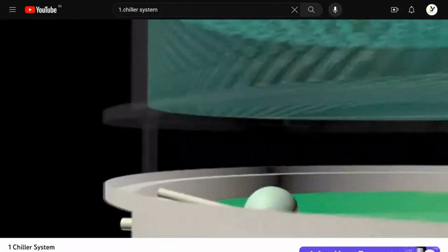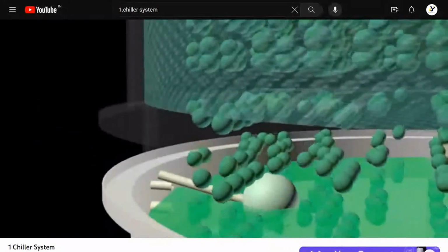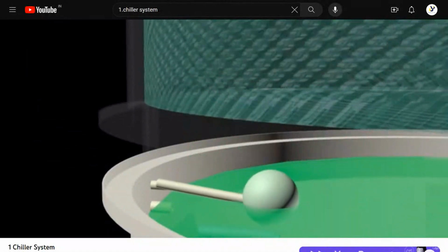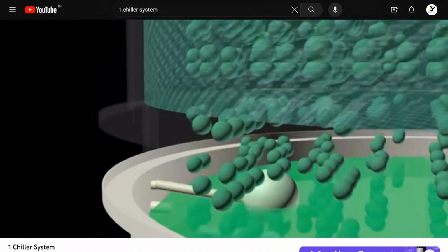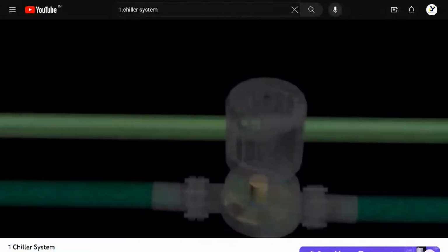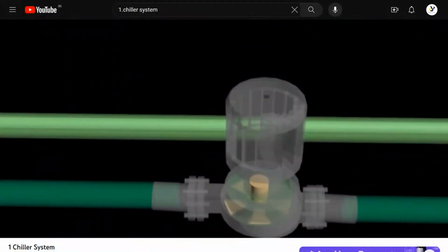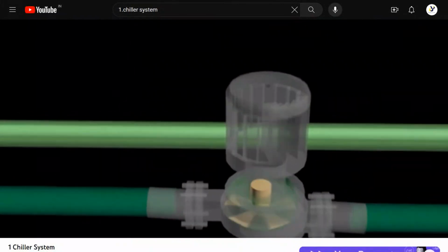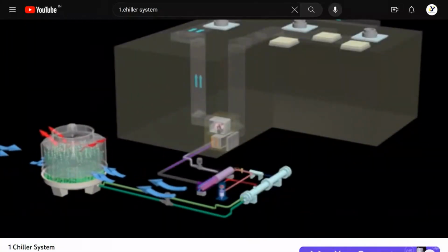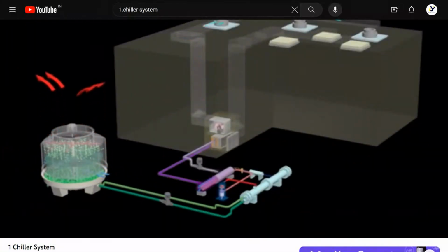The buoy system at the water basin is connected to the make-up water tank. It works for adding water when the water level in the basin decreases to a certain level due to evaporation. This condenser water cycle will continuously flow as long as the centrifugal pump is in good working condition. This explanation hopefully will enhance the students' comprehension regarding the centralized air conditioning system.